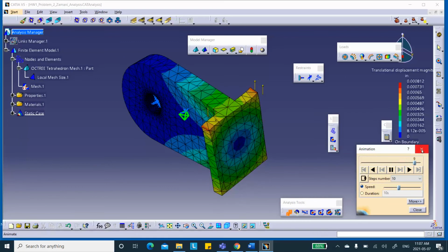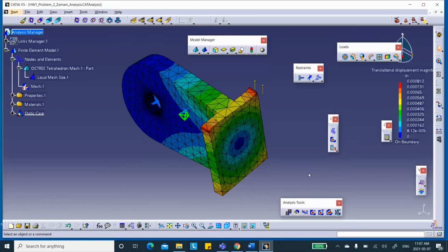You're not addressing the issue of is this fine enough or etc. Also, edge loads are impossible to apply in real life, and so are the concentrated. There is no such a thing as concentrated load, edge load. Okay, but you can apply. So the effect, of course, is a gigantic stress in this area, which may be not realistic.